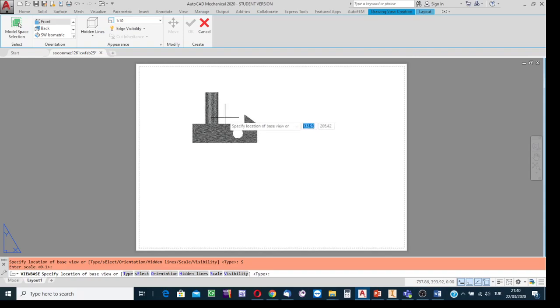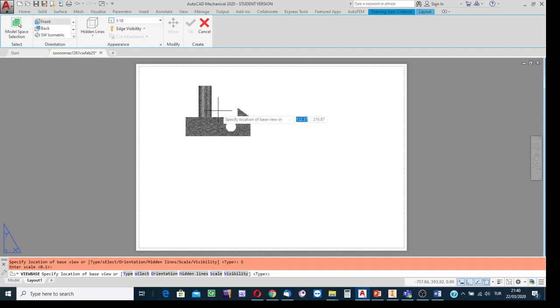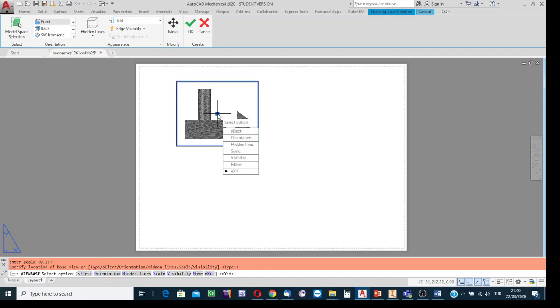Okay, and then locate the view. If it is first quadrant projection, you should know that the front view is created over the paper, or it is shown on the paper, not any other place but there. If there will be three views as front, top, left, then the front view is created using such a part of the drawing paper. So move the cursor to that location together with the simulation, of course, and then with a click anchor it over there. Say that it is the place for the front view,